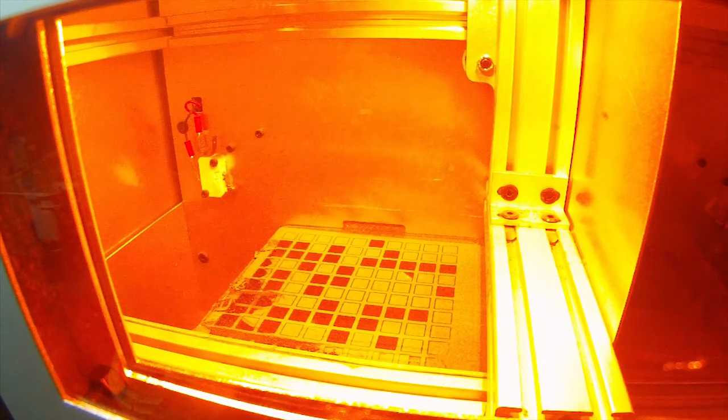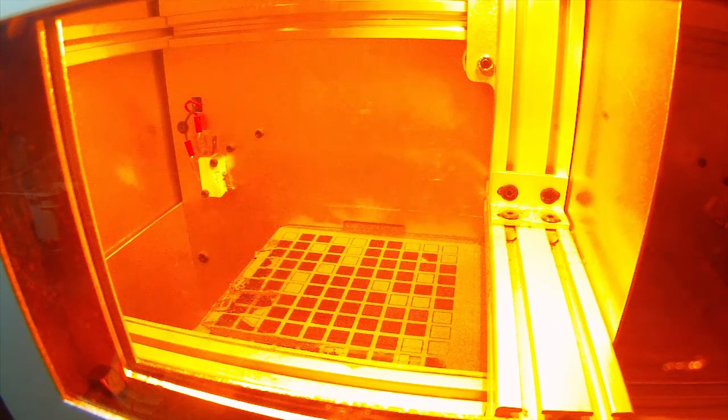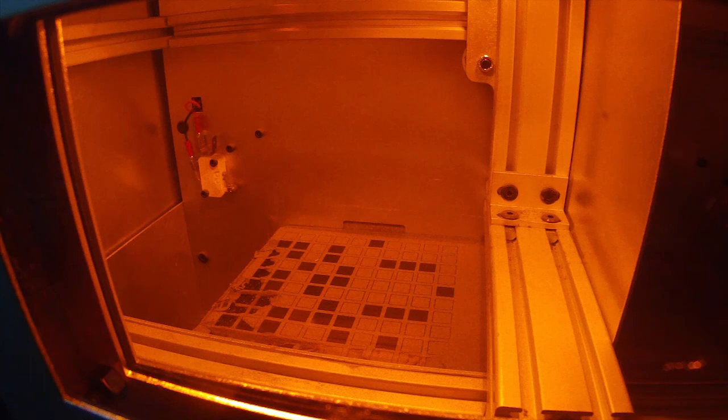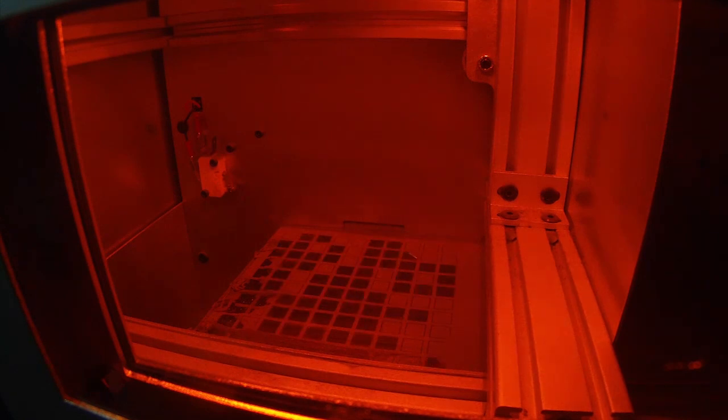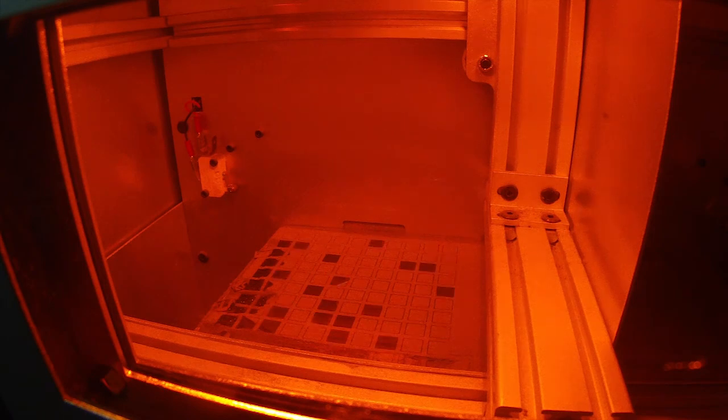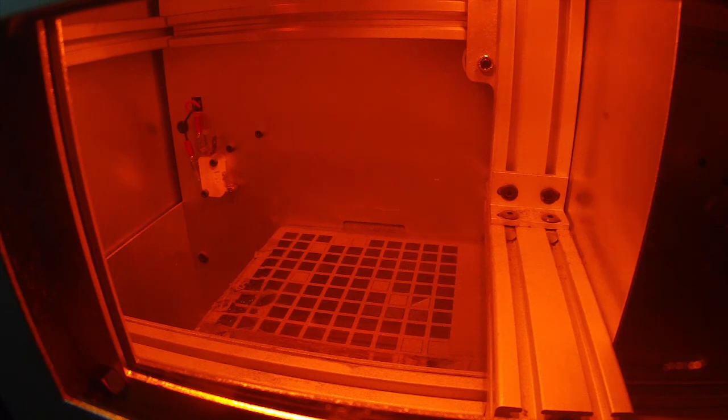I went 174. You can work with 174, and then you can get a really big footprint, but it's a lot of work, especially if you have interconnected parts, or if you have any parts that have little channels or little tubes. It's over with. The powder in there is fused. If you have a simple model that doesn't have a lot of internal geometry, then maybe you can go that high in the center, but your parts next to each other will fuse together, and there'll be this buildup, this plaque along the outside. So that's kind of the things you need to look at when you take it apart.